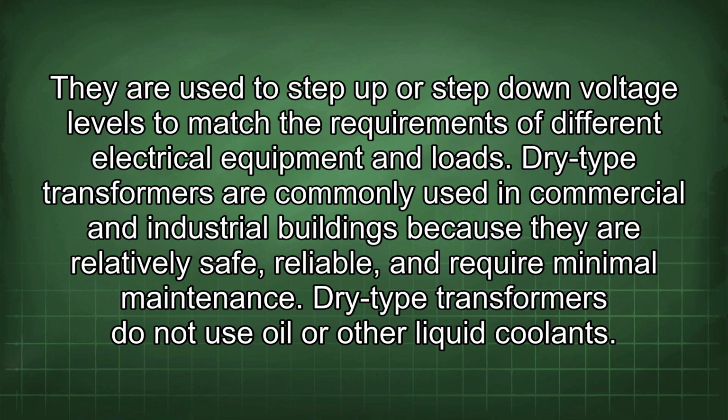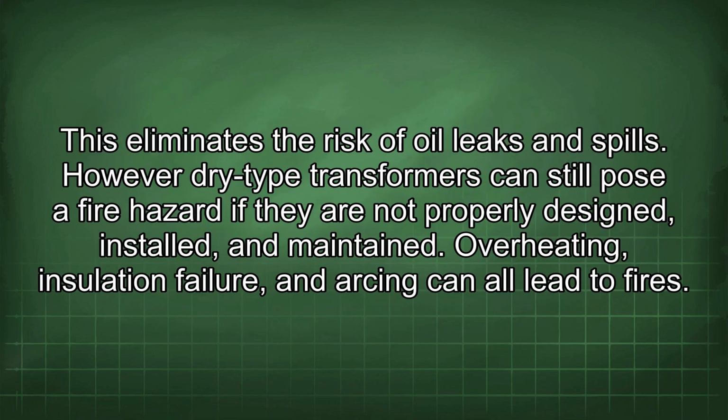Dry-type transformers are commonly used in commercial and industrial buildings because they are relatively safe, reliable, and require minimal maintenance. Dry-type transformers do not use oil or other liquid coolants. This eliminates the risk of oil leaks and spills. However, dry-type transformers can still pose a fire hazard if they are not properly designed, installed, and maintained. Overheating, insulation failure, and arcing can all lead to fires.